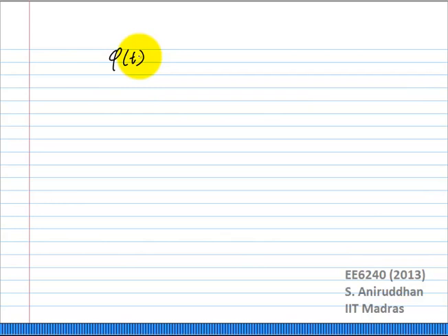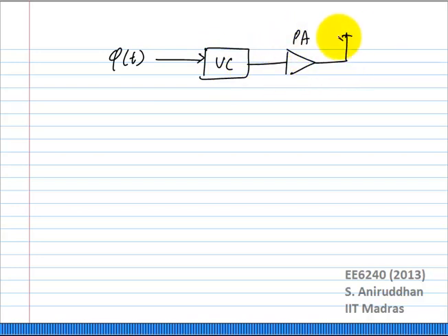What do I need to do to transmit this signal? I need to upconvert it, correct? I probably need to amplify it so that the received signal strength is very large. Anything else? I need to upconvert it and maybe amplify it before I send it into an antenna. Anything else?